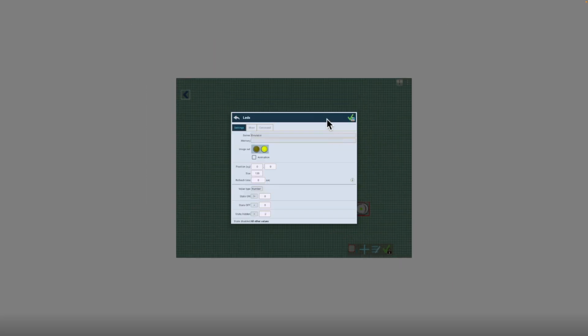The status of the LED can be associated to different values of the variables. You can even make the LED disappear. This is going to happen with almost every component. The LED can be made to disappear if the variable contains a value, in this case, for example, if it is equal to -2. If we put a -2 in the variable that we associate with this component, the component will disappear from the screen.